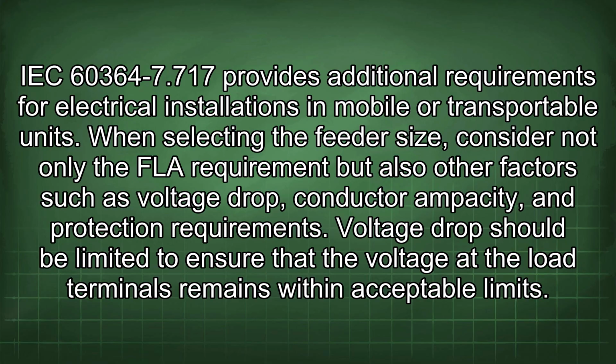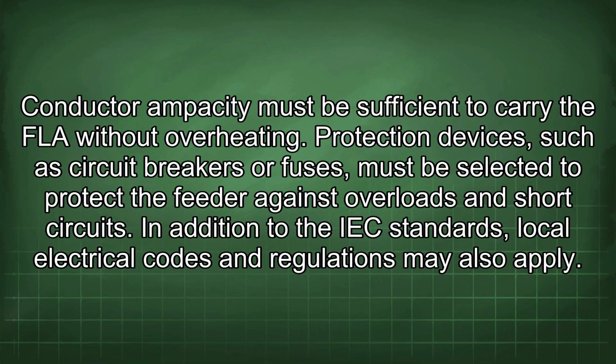When selecting the feeder size, consider not only the FLA requirement but also factors such as voltage drop, conductor ampacity, and protection requirements. Voltage drop should be limited to ensure that the voltage at the load terminals remains within acceptable limits. Conductor ampacity must be sufficient to carry the FLA without overheating. Protection devices, such as circuit breakers or fuses, must be selected to protect the feeder against overloads and short circuits.